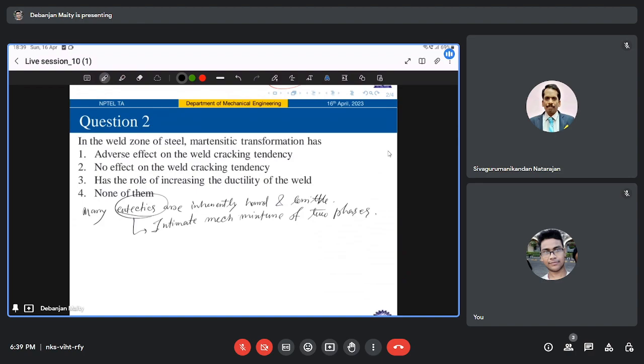And second is that the interface between these two phases is extensive, right? Often in the form of alternating layers in what are called lamellar eutectics. So the large shared interface between an inherently tough phase and an inherently brittle phase inevitably limits the toughness of the combination. Correct. The reason is that for loading along or parallel to the lamella of this lamellar eutectic, the maximum strain that can be tolerated is limited by the less ductile phase, right?